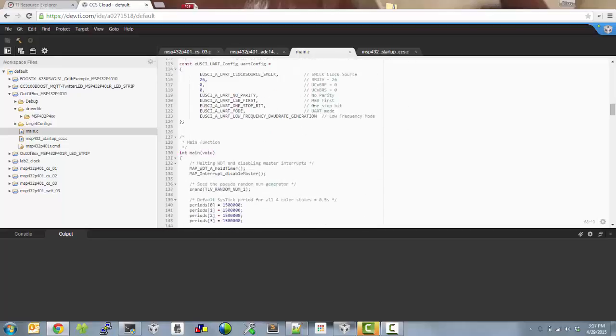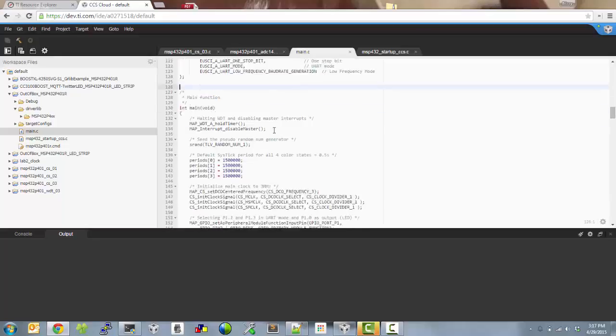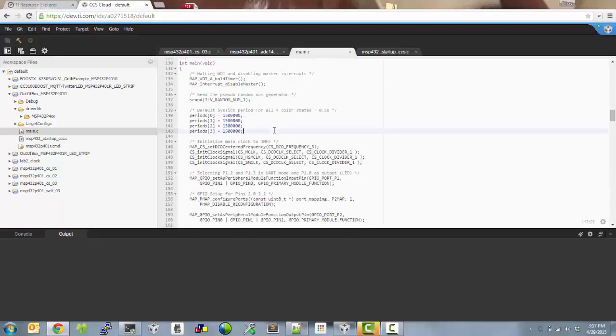So once you view the code and navigate it, make the edits necessary, once you're done with the development, you can start compiling the code on the cloud and then download to the device. If you look at the top menu items, you might see that there are 2 icons here. The hammer, which is used to build the project, and once the project is built, you can click on the green icon to run. So let's go ahead and get started building the project.